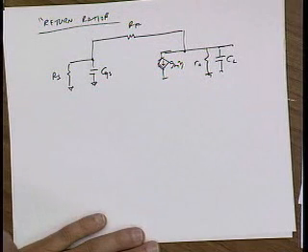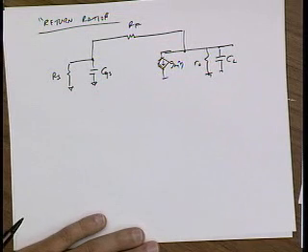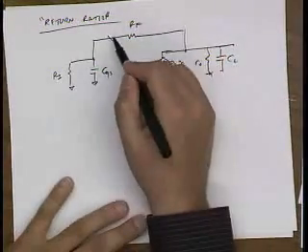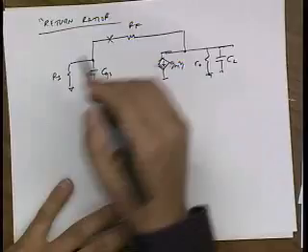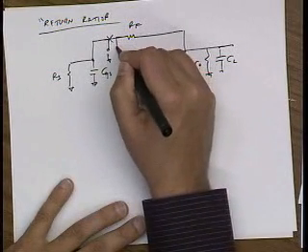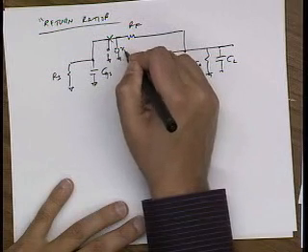That should be the actual loop gain. So what's the problem for doing that? Why can't I just break the loop? Let's say I'm going to break the loop over here and basically observe this voltage when I drive this voltage with a test source.